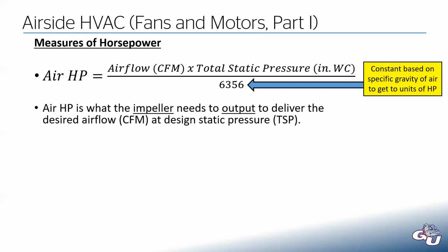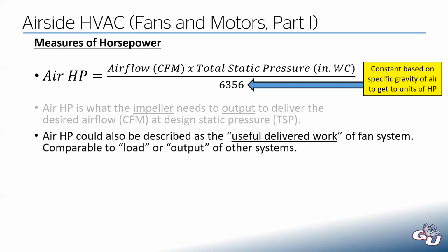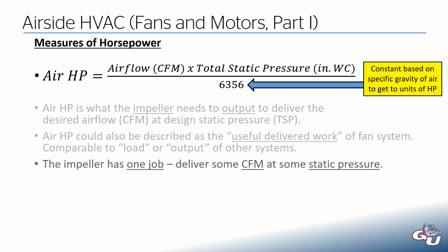Another way to word that is, what's the useful delivered work? And so this could be comparable to thinking of a load or an output of other systems. This is the final output of a fan. How much air and how much pressure. And that's the impeller's one job, to deliver that CFM at that static pressure.